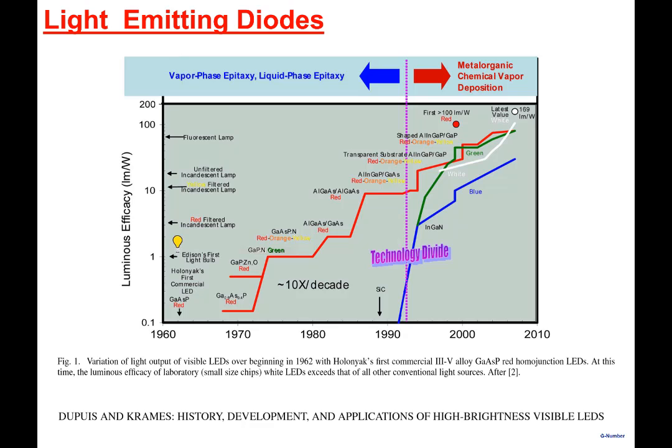The other one is that LCD was a slow technology. Slow in the sense that the response time is slow, because it's actually a liquid crystal. When you apply a voltage, the liquid crystal twists and becomes opaque. When you apply a different voltage, the liquid crystal may untwist. So it's like a physical motion of a liquid crystal, and that makes it slow. If you have an LCD cell which is opaque and you suddenly want to turn it transparent, it would take milliseconds to really turn transparent.